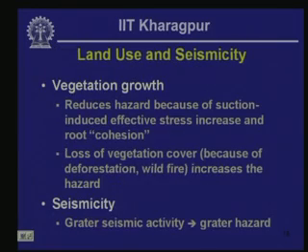So, you have to look at very small area units in hilly areas in terms of microclimate in order to assess the landslide likelihood in that area, because of the variation in the prevailing microclimate.